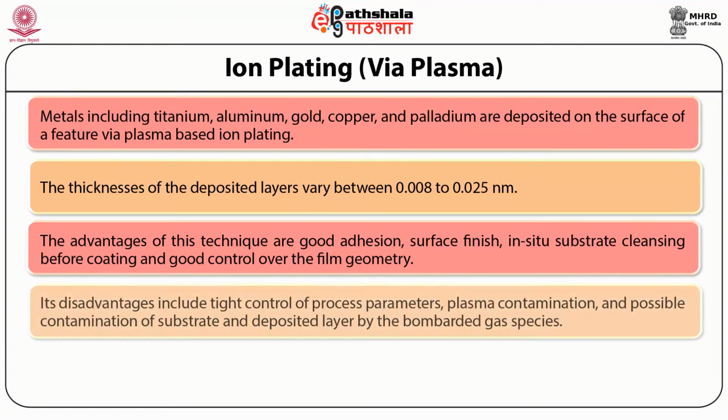However, its disadvantages include tight control of process parameters, plasma contamination, and possible contamination of substrate and deposited layer by the bombarded gas species.